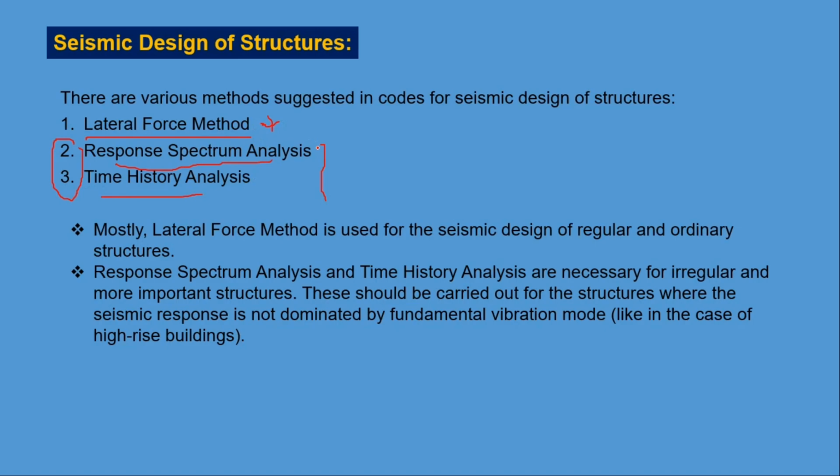And in codes, as we consider mostly linear analysis, for economic consideration we have to reduce the force, and we use various factors like the response modification factor. Building codes do not explicitly mention carrying out nonlinear analysis. Rather, they suggest that we modify by using such factors.